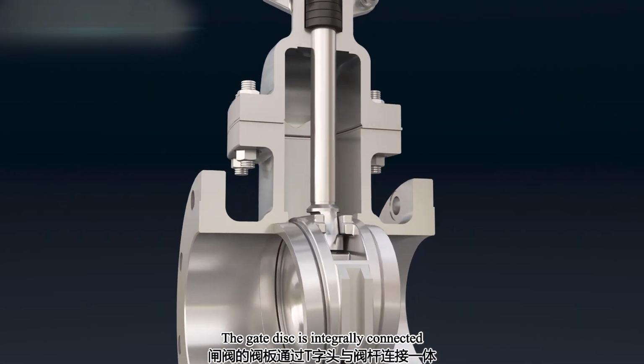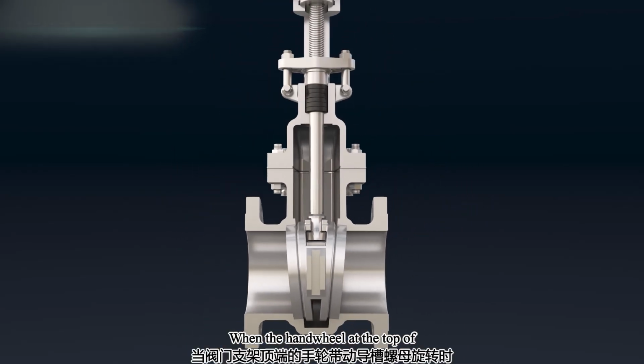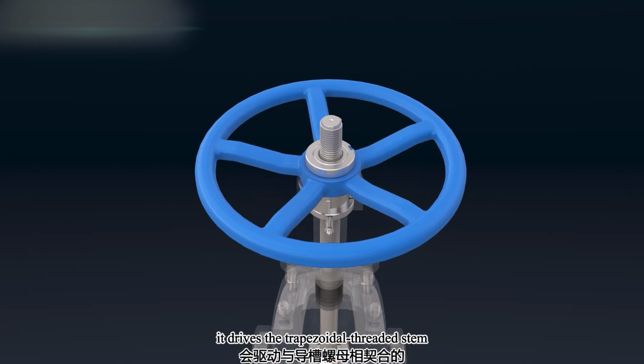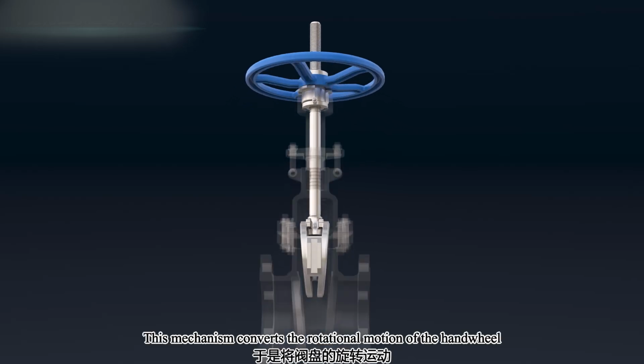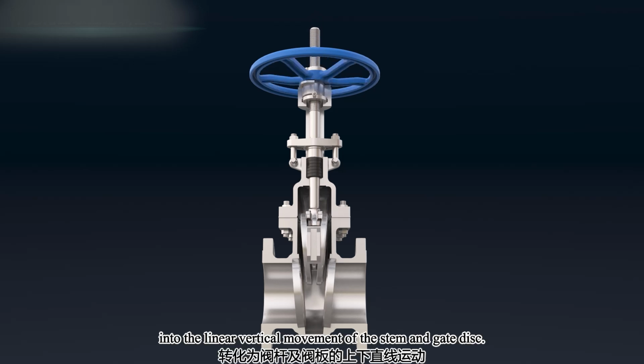The gate disc is integrally connected to the stem via a T-head joint. When the hand wheel at the top of the valve yoke rotates the guide nut, it drives the trapezoidal threaded stem, engaged with the nut, to move vertically. This mechanism converts the rotational motion of the hand wheel into the linear vertical movement of the stem and gate disc.